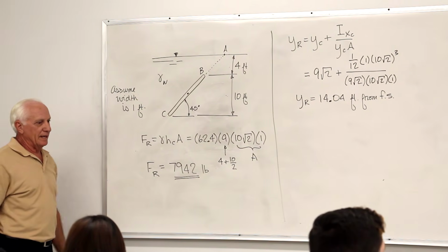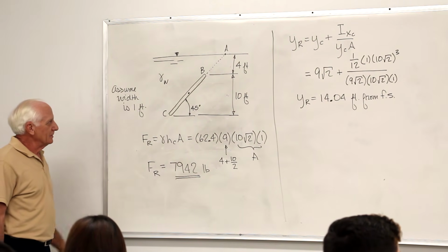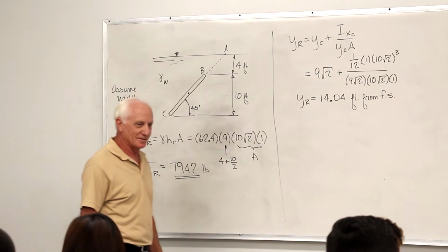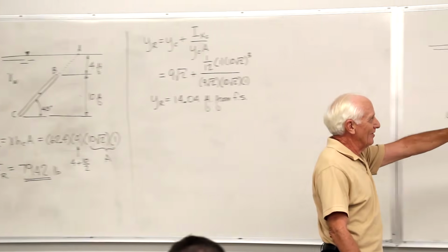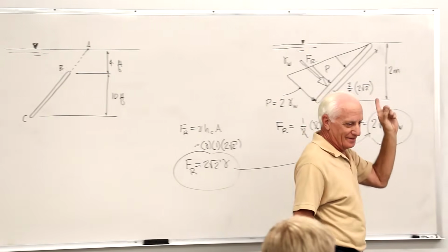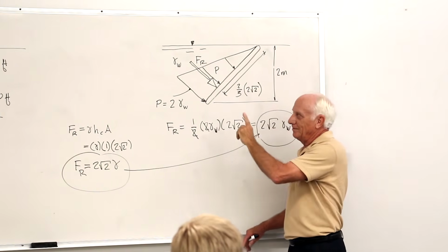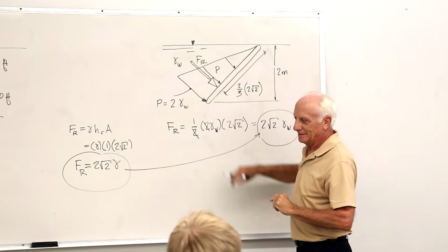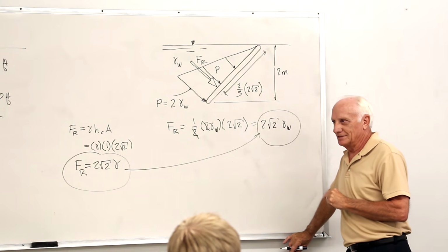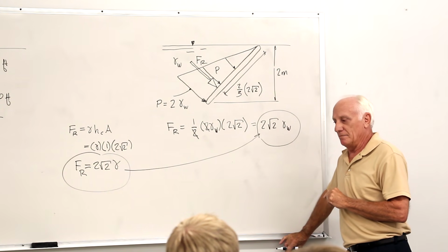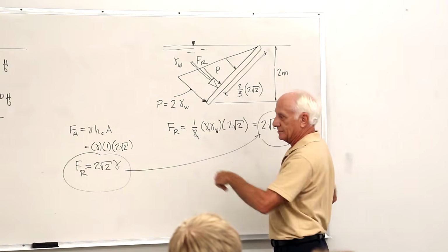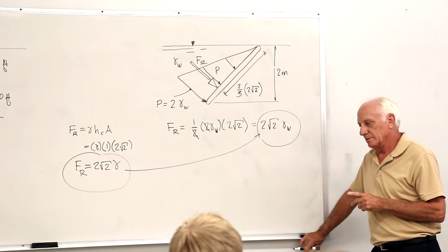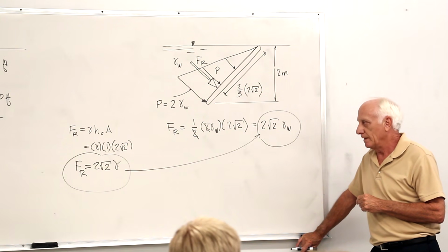Can the surface be triangular? Yes. Can the surface be circular? Yes. Semicircular? Yes. Quarter circular? Yes. This method right here, you've got to be really, really careful. It's only good for what we did here with this showing right here. That's only for rectangles. Triangles, no. Circles, no. Is it maybe easier to do like you did back in statics? Maybe. But you've got to watch out where you use it, because you can misuse it just as easily.